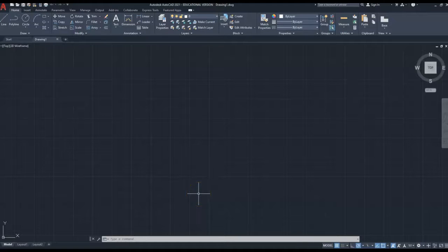In construction we use millimeters. Luckily the default setting for this particular type of AutoCAD is millimeters, so we haven't got to change any of the units. But that is an option. Again, we'll pick that up when we want to set up pages for specific things. So let's start with some very simple techniques. First of all, ideally you've got a 3-button mouse: a left click, a right click, and a wheel as your third button in the middle. That's going to give you the most flexibility when using AutoCAD, which you'll see as I move my way around.